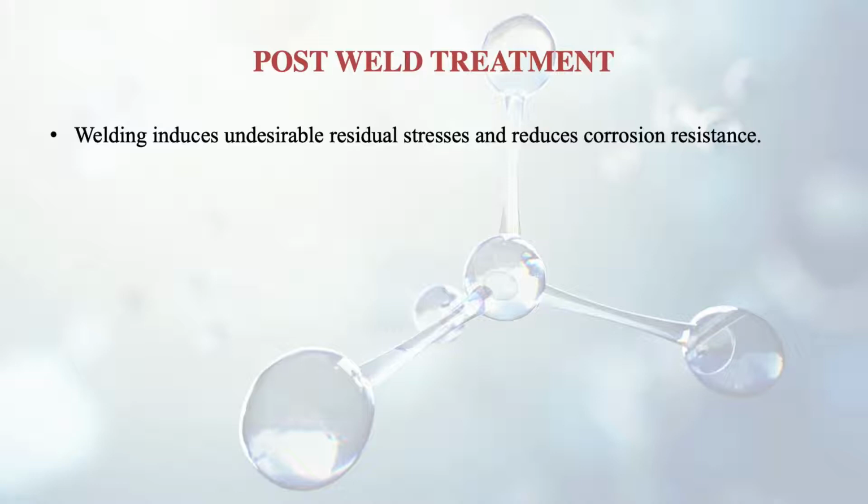Further, now we discuss the post-weld treatment. We earlier saw how weldability is affected in many cases, so we need post-weld treatment also. Welding, we know, induces undesirable residual stresses, and thus the corrosion resistance is reduced.